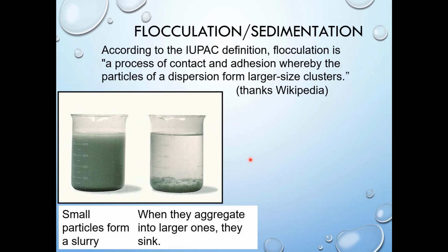Nice. Whatever. What's going on with flocculation is that you start off with small particles, and they are attracted to dirt and ions and some other stuff that you might find in your water that you want to get rid of. With very, very slow mixing, they aggregate to each other to form larger particles, which naturally become very, very heavy. And so they sink to the bottom of your container, and that leaves behind all this lovely fresh water. All you've got to do is pour it off, and then all of this gunk at the bottom just needs to be disposed of.